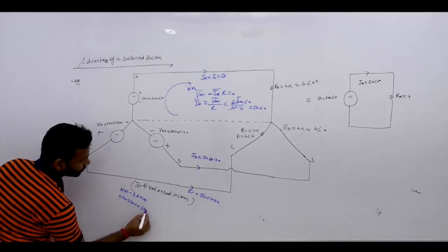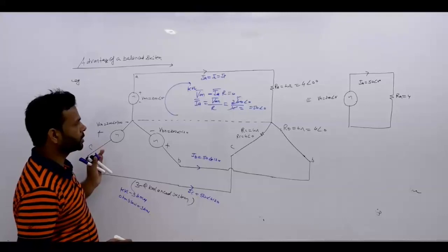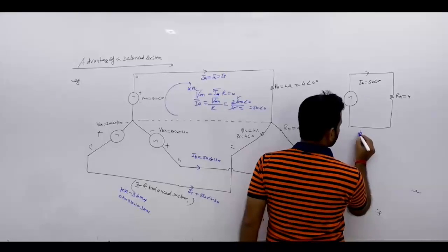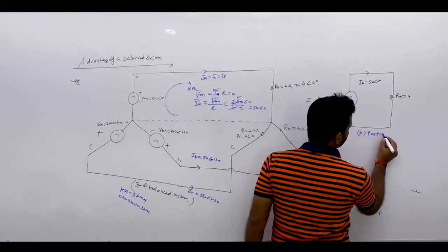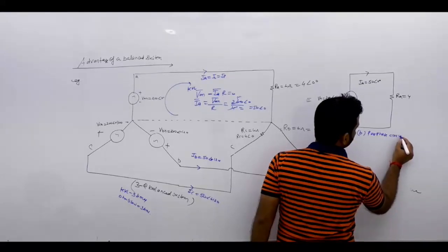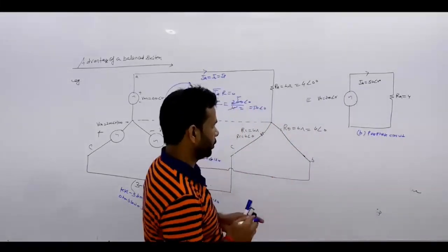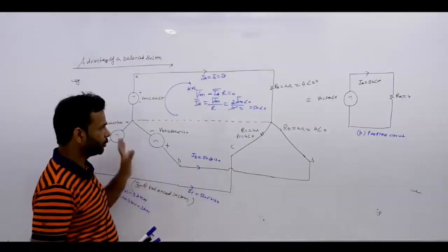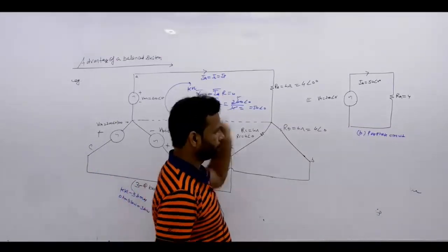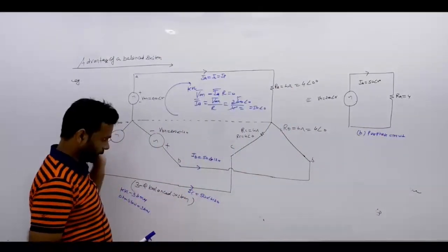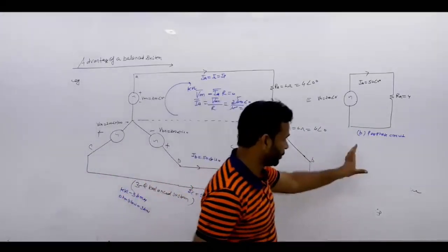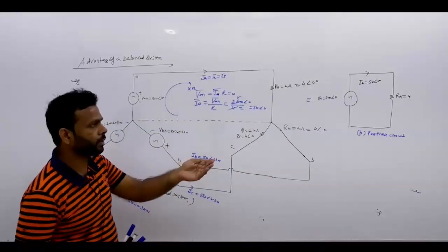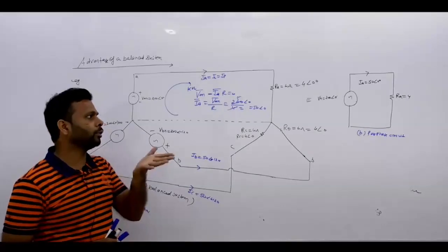3 times. Okay. But when you express your three-phase balanced circuit into a per phase circuit, what's the meaning? If you draw your three-phase balanced circuit into a per phase circuit, then your circuit complexity reduces. We can reduce the number of KVL, KCL, as well as Ohm's law. And from the per phase circuit knowledge, you can have all the three-phase knowledge.